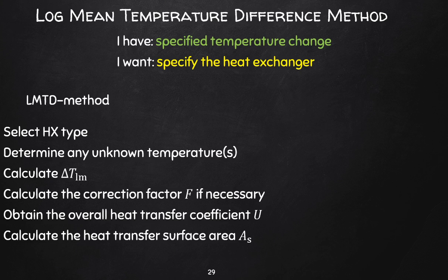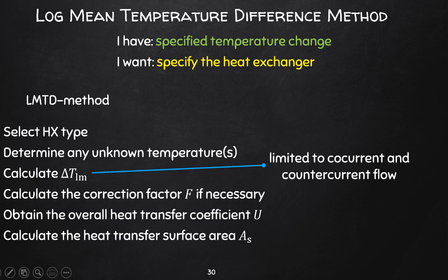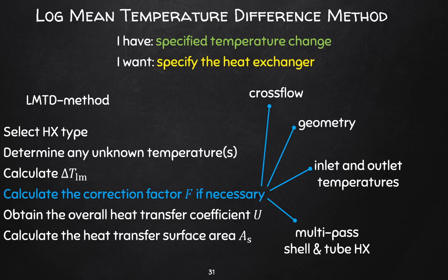Now typically we would want to design a shell and tube heat exchanger with very thin walls, but if you're working with high pressures, don't do it. Just design safely at least. Just keep in mind that the log mean temperature difference only applies to co- and countercurrent heat exchange applications. So if you don't have these sorts of flow configurations, then you would just generally determine a normal delta T in that regard.